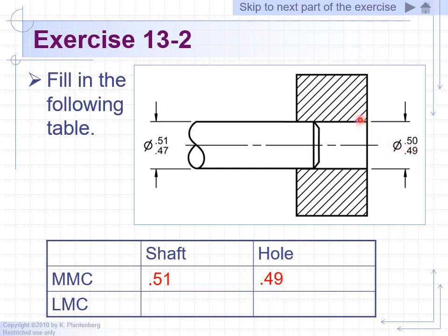If you were to drill up to a 0.50 diameter, then you're removing more material. So that's when you have less material, when you drill at the maximum diameter. When you drill with the smallest diameter hole allowed, then you leave behind more material. So the maximum material for this block, or when it's at its heaviest, is when you're dealing with the smallest diameter allowed of 0.49.